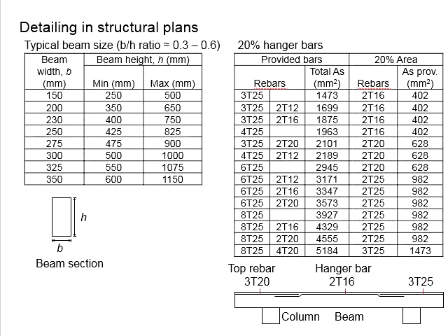This will lead to a situation where the support is quite heavily reinforced, while the midspan appears relatively weak. This will lead to a situation in the distribution of the stress, especially when the member is reaching its capacity, where there will be concentrations of stress at the weakest portions of the member.